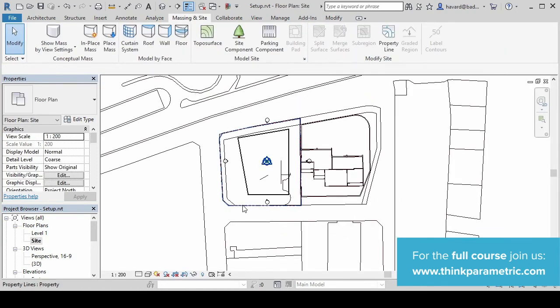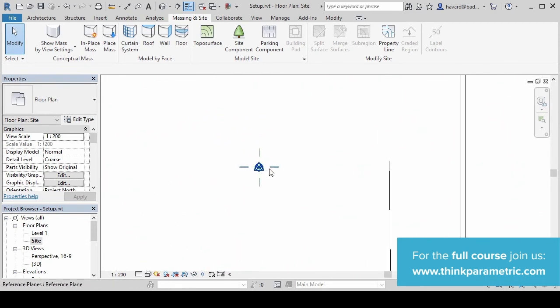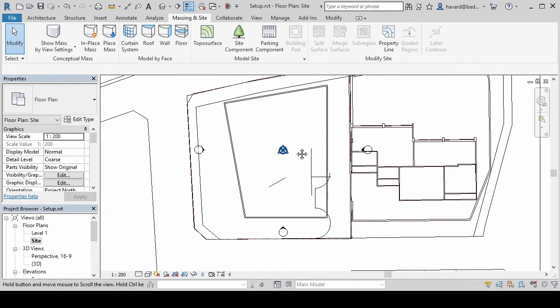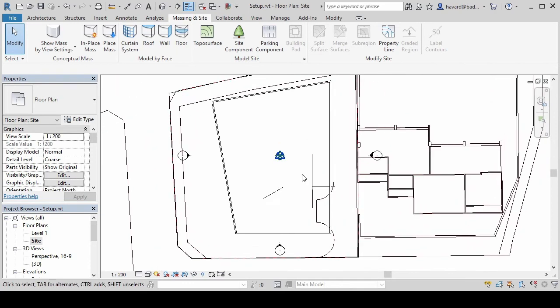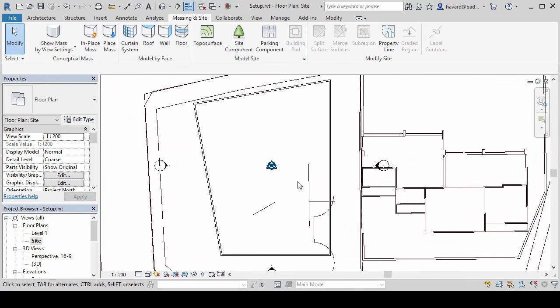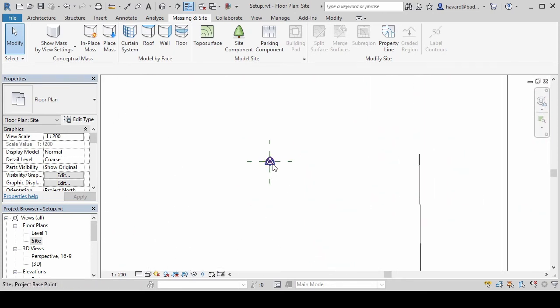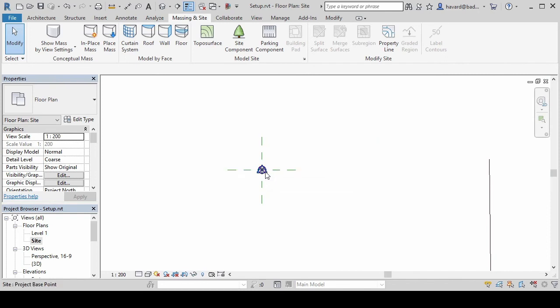So we want to make sure that that setting also gets transferred to the Revit system. Go back to the site view. Actually, this is a pretty good case where we want to look at the updating of CAD files because I didn't export the origin line work from the Rhino file.